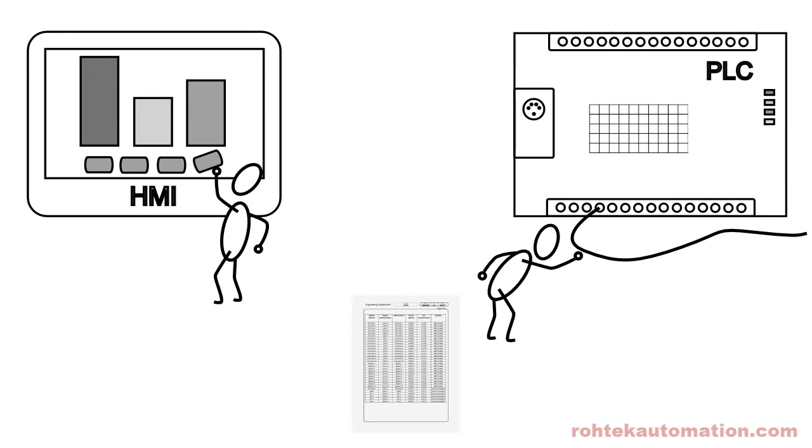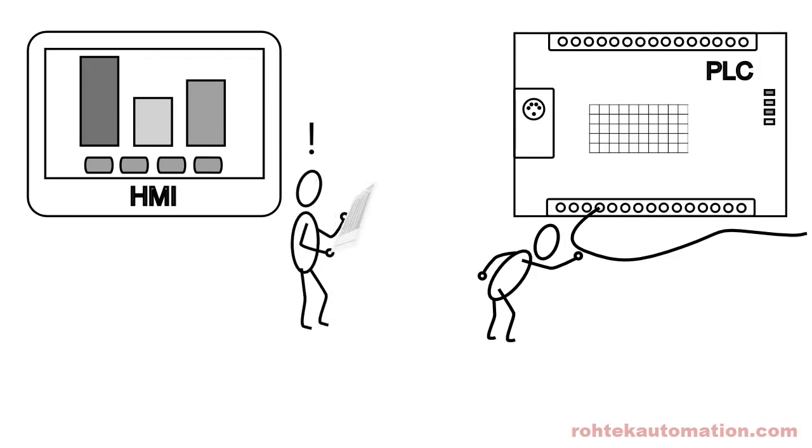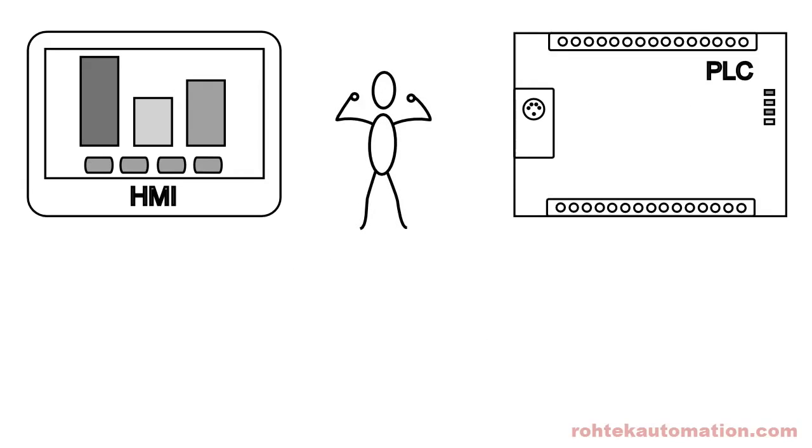The interface table is a clear method of communication between those working on the PLC program and those programming the HMIs. With a well-documented interface table, those working on HMI code don't need to know about every little change being made to the PLC program and don't have to be concerned about exactly how, for example, the I/O is implemented, be it embedded, expansion, or remote I/O, etc. And even if you are the only one programming the system and somehow are the only one who ever has to maintain it, you'll appreciate not having to relearn the intricacies of the PLC program and I/O structure just to make a small change to the HMI program.